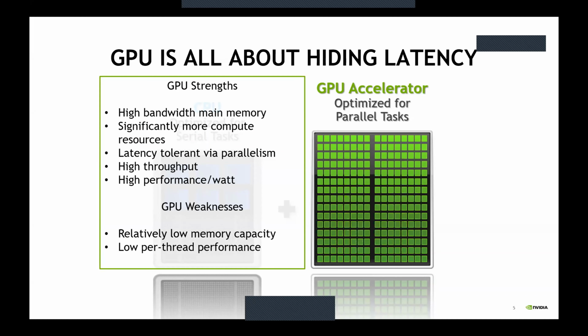And thus, the more work we can give the GPU to do, the easier it is for the scheduler to hide this latency. So we'd actually need many overlapping concurrent threads. To support this, the GPUs have a very large register file to hold the state of the threads, and actually switching between the threads happens at no time penalty, even as often as every clock cycle. As such, the significant majority of the silicon on GPU can be given over to computation rather than data movement, which is what gives them a very efficient performance per watt.